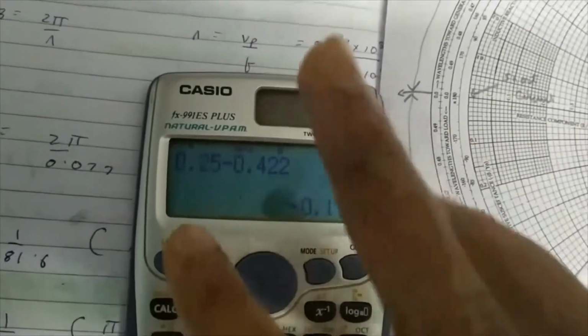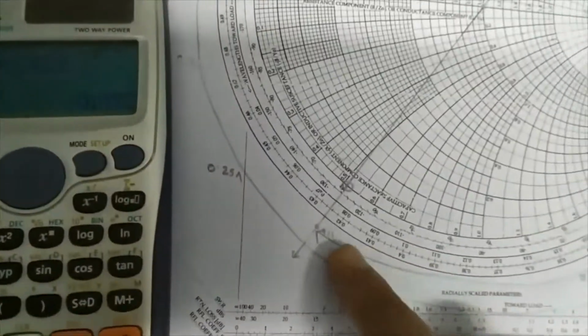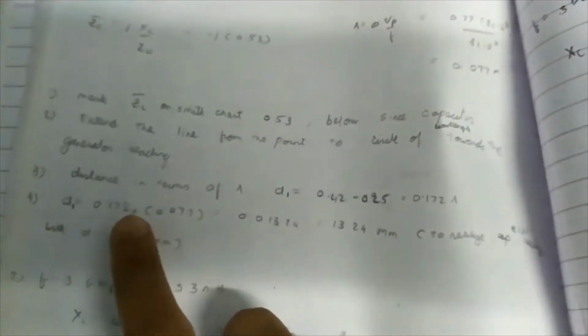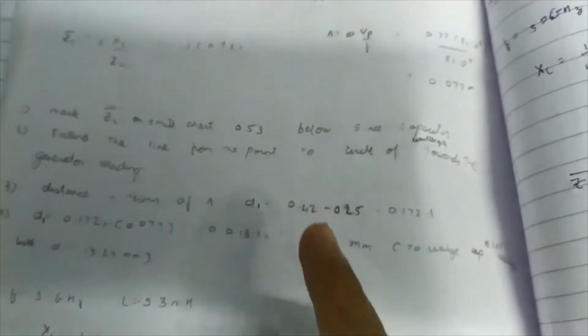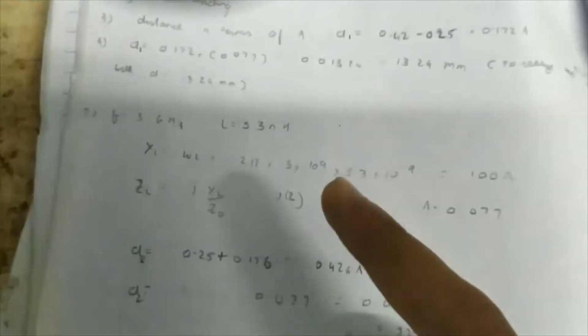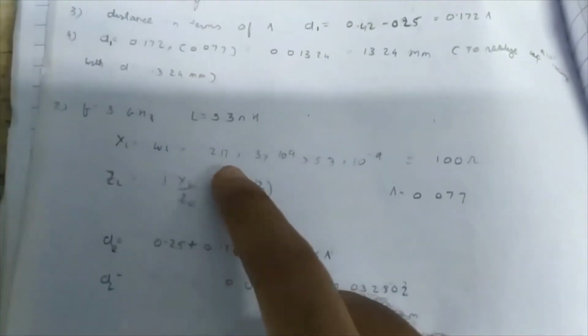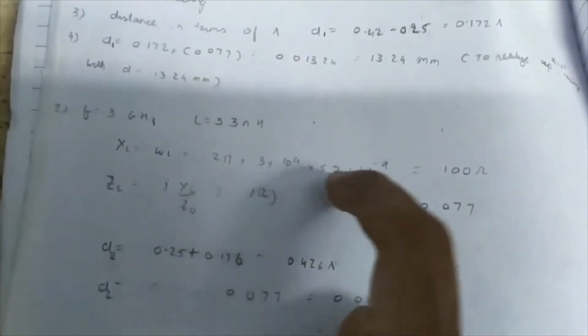So I've subtracted this point minus this point, and you get 0.172 lambda. Next, to find the distance, you just have to multiply with the wavelength and you get the distance as 13.24 millimeter. Similarly, to convert it into an inductor, find the impedance of an inductor, which is given by this formula,